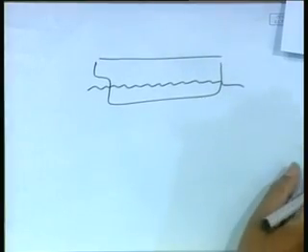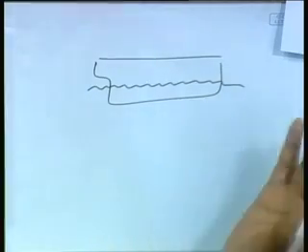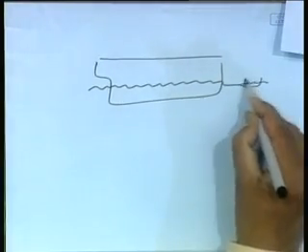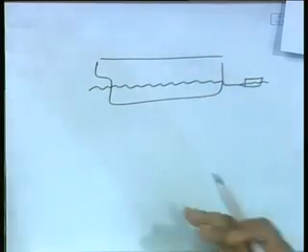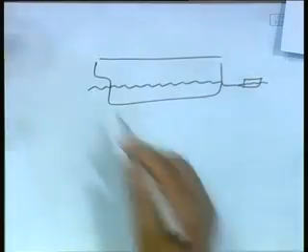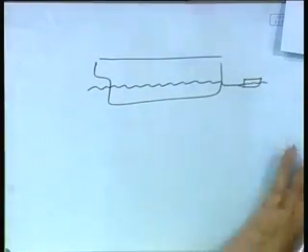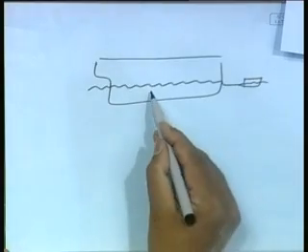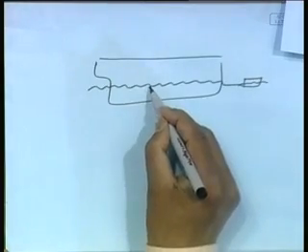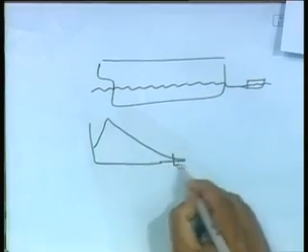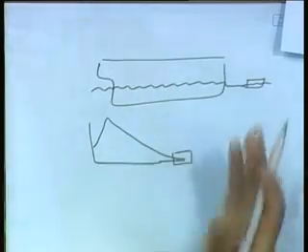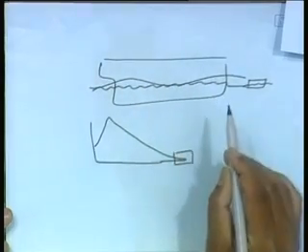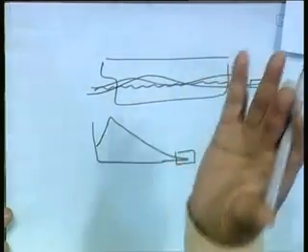As an example, if you ever go to a port, you will find there is a large ship. You will see some small ripples, and I used to always wonder personally that in such cases the ship does not even move up and down, and there is a small boat next to it. It is as if the ship is grounded. I used to wonder that this ship seems grounded, these waves are flashing by and the ship does not move, while a small boat here is sloshing up and down. So that means it is so high frequency, the inertia is in this region for this ship, that it does not have any force to move up and down at all, but slightly more and something like that, it will now begin to move up and down.